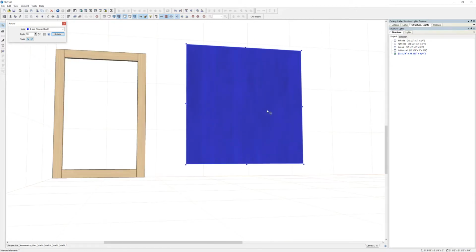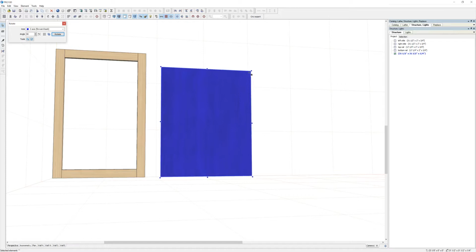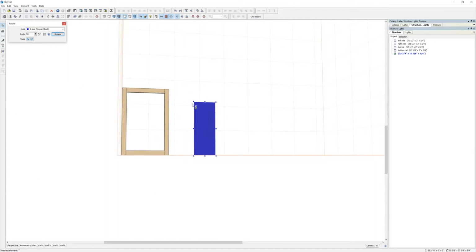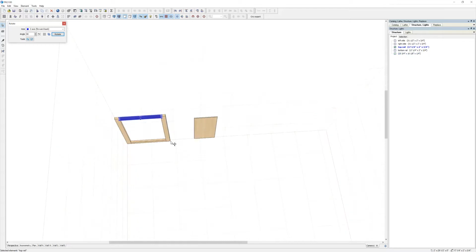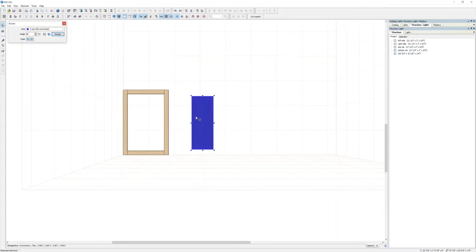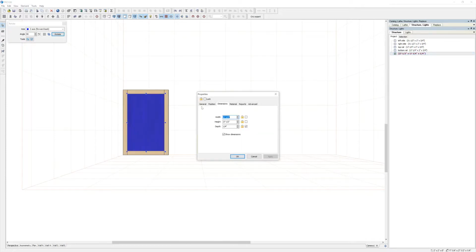So now I'm gonna resize this in the hole so that I can put it in here. So I'm holding down my shift, and this is against the wall. Hold down your shift to override collision. There you go, and then stretch it. So that's going to be, it's not named yet, it's right here. I can call it now glass.